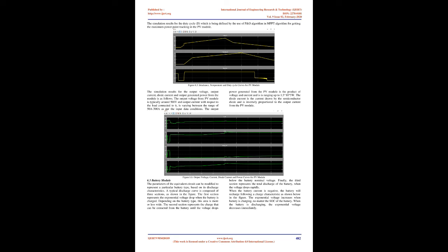4.3.3 Controlled Voltage Source Model. Accurate modeling of a battery is a very complex process that requires knowledge of the electrochemical processes within. For crude energy simulation purposes, a model that accounts for the varying voltage that is available based on the SOC can be sufficient. The model presented in this section uses only the SOC as a state variable. The voltage is modeled by a controlled voltage source that is dependent on the SOC as shown in equation 2. The explanation of the variables in the following equations and circuit diagrams is available.